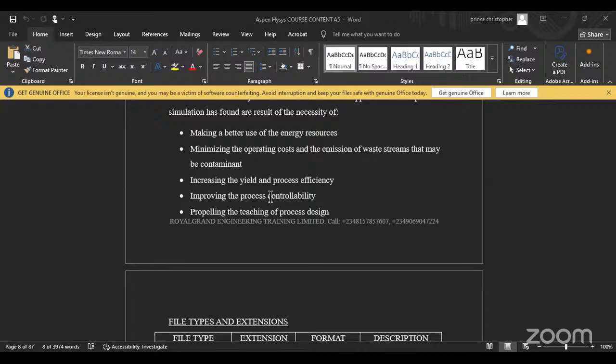Okay, rule of thumb, for natural gas and crude oil we have Peng Robinson and SRK. So what are the components we selected? Okay, the components we selected, these are hydrocarbons. They are mostly hydrocarbons, apart from water.